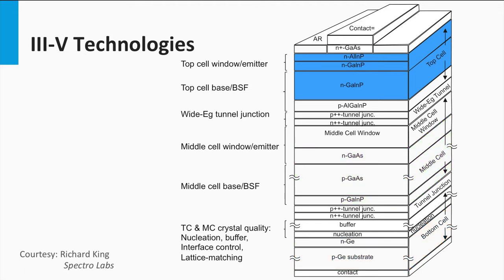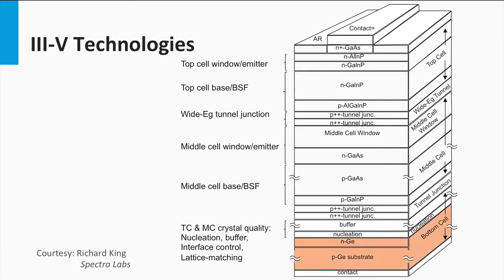The p-n junction at the window layer at which the solar light enters the PV device is called the top cell. As the spectral part with the most energetic photons like blue light has the smallest penetration depth in materials, the high bandgap junction always acts like the top cell. As the near-infrared light outside the visible spectrum has the largest penetration depth, the bottom cell is the cell with the lowest bandgap. This cell has to harvest the photons from the spectral part with the lower energetic photons.